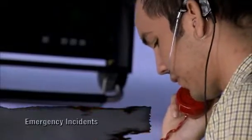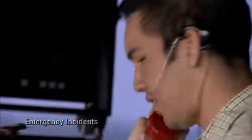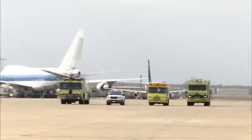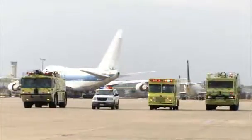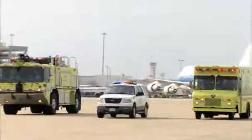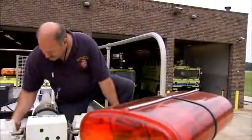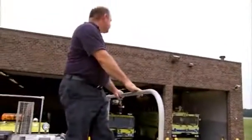In an emergency, air traffic control will often restrict ground movement and radio traffic on the ground frequency. Air traffic control personnel can often inform ARFF personnel of the type of aircraft, the type of alert or emergency situation, the number of people, and amount of fuel on board and other useful information. Based on this information, ARFF personnel should have the discretion to upgrade or downgrade the alert level. If necessary, repeat the information over fire frequencies and the PA system to alert other ARFF personnel.